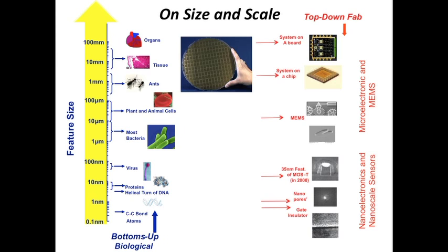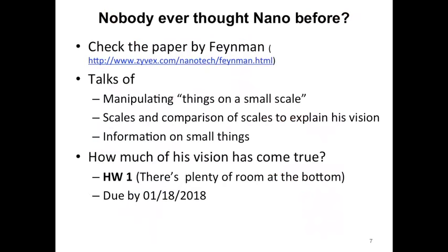But the idea is, yes, making a pore in a film, only one pore, 5 nanometer, is not an easy task. It's really challenging, because making a pore with good reliability and making sure it's only 5 nanometer is complicated. But there are ways to do it, which we'll cover later. The whole idea is that for various applications, we really need features and structures at the nanoscale, because large scale structures don't work. This is one example in sensing, and there are quite a few examples in other areas like therapeutics and even nanophotonics.